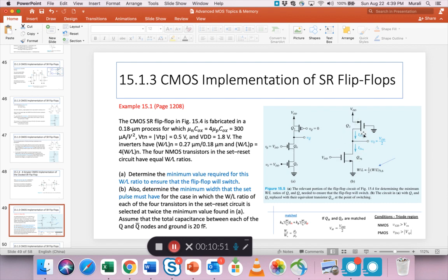And this is kind of a no load condition, so we assume the same current is flowing in the two drains. So notice how he sets up the equation for IDEQ equals ID2. And one more important thing is that both these transistors are in the triode region. Why are they in the triode region? He hasn't explained too clearly, he just says it's there, but I have tried to give you the conditions.